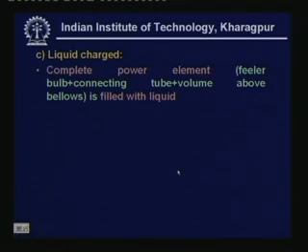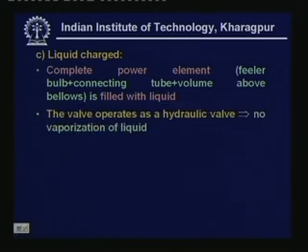Liquid charge means here the complete power element, that means the feeler bulb plus connecting tube plus volume above the bellows is filled with liquid. Once you fill it with liquid, the valve simply operates as a hydraulic valve and there is no vaporization of liquid. And when do you use this kind of valve?